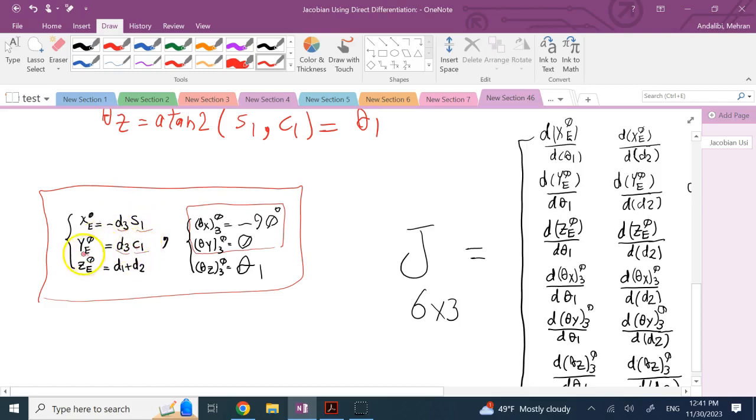So if I set my x dot and y dot, that means the values of omega 1 and d3 dot are already taken care of. And if I set my z dot, then the d2 dot is also taken care of. So the theta z dot, which is omega 1, is automatically going to be determined from these 2. So I don't have 4 independent velocities, and I cannot have, because my robot has only 3 degrees of freedom.